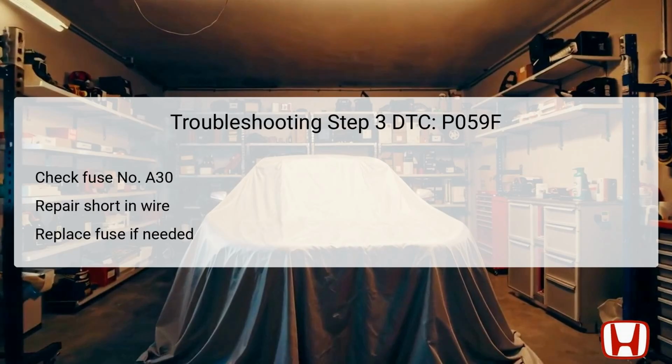However, if the fuse is blown, it is necessary to track down and repair any shorts in the +B shutter grille upper wire between the grille and the A30 fuse. After addressing any issues, replace the blown fuse to restore electrical integrity. This step helps ensure that power is reaching the actuator and that it can function as intended.